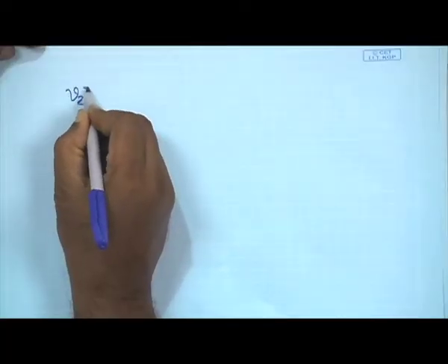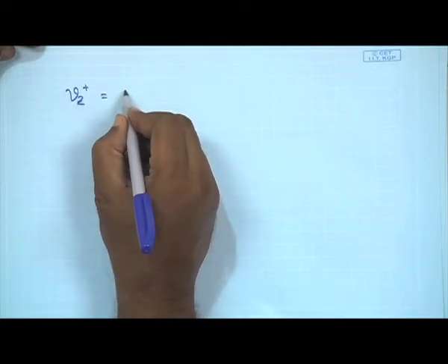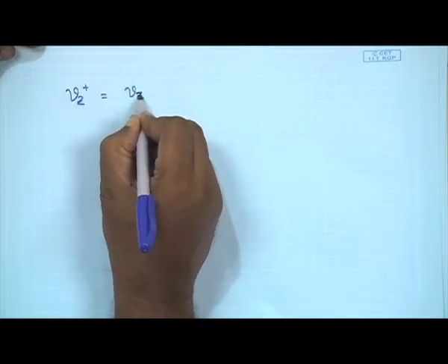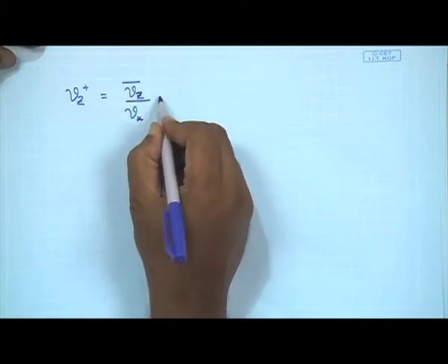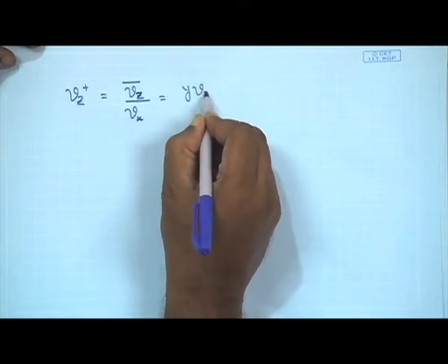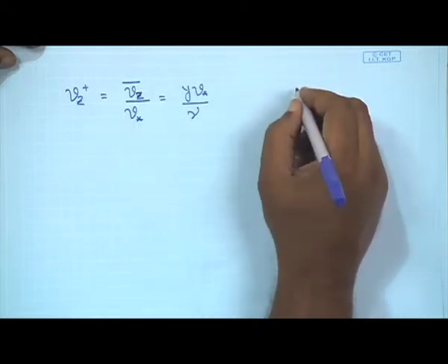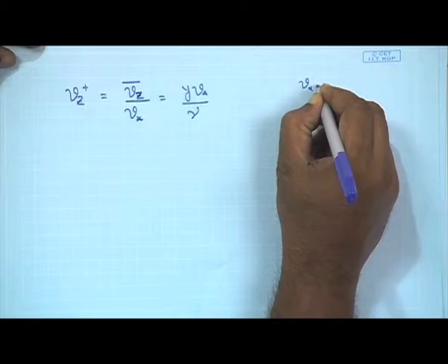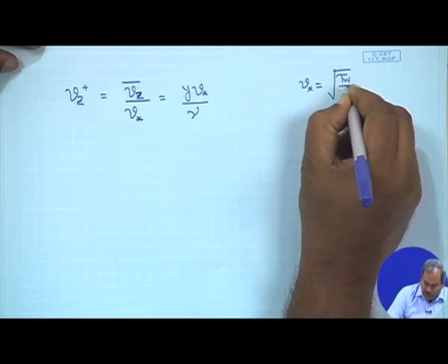First is the viscous sublayer, where Vz plus, the velocity, the axial component of velocity in dimensionless form, which is Vz by v star, where Vz is the time smooth velocity, is equal to y v star by nu, the kinematic viscosity, and this v star is essentially root over tau w by rho.